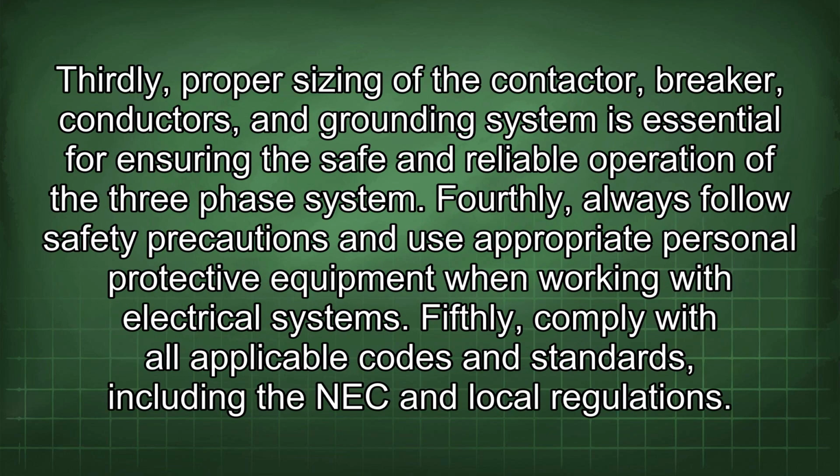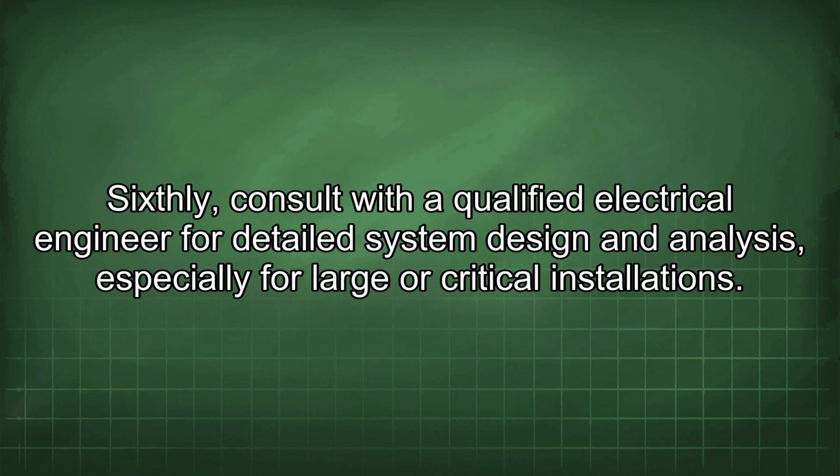Thirdly, proper sizing of the contactor, breaker, conductors, and grounding system is essential for ensuring the safe and reliable operation of the three-phase system. Fourthly, always follow safety precautions and use appropriate personal protective equipment when working with electrical systems. Fifthly, comply with all applicable codes and standards, including the NEC and local regulations. Sixthly, consult with a qualified electrical engineer for detailed system design and analysis, especially for large or critical installations.